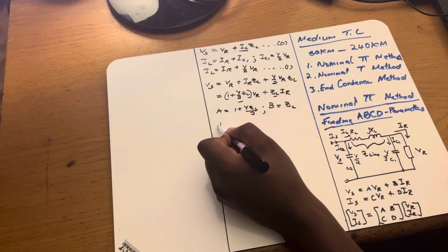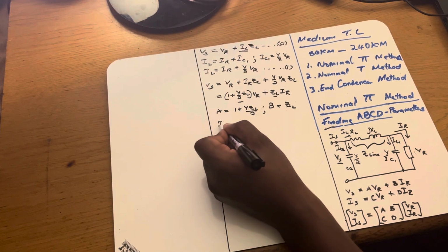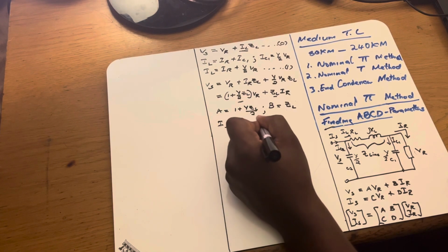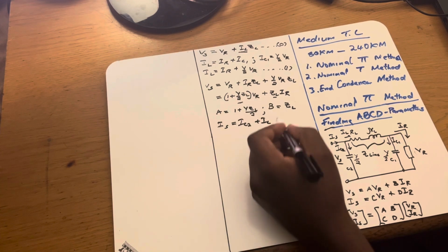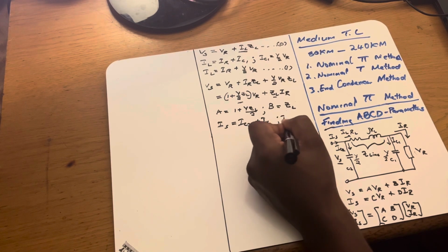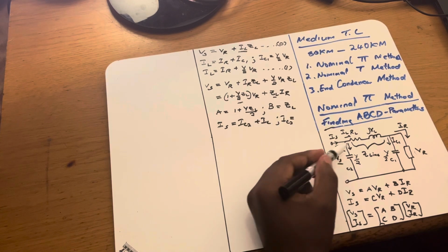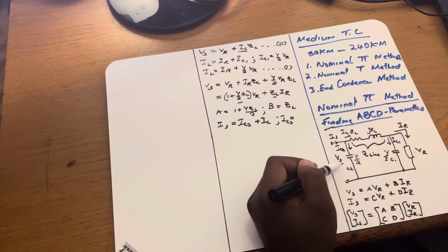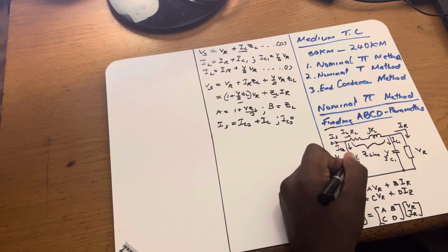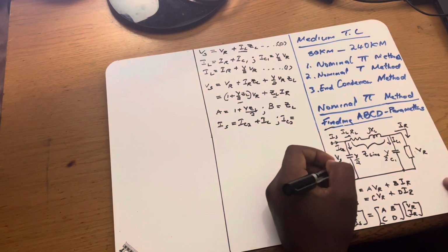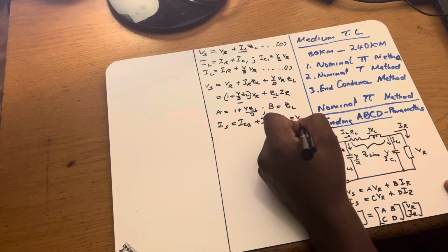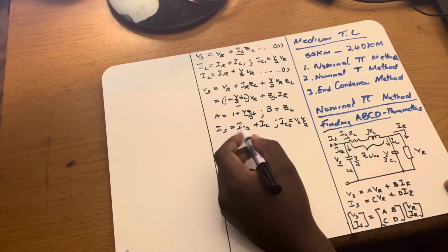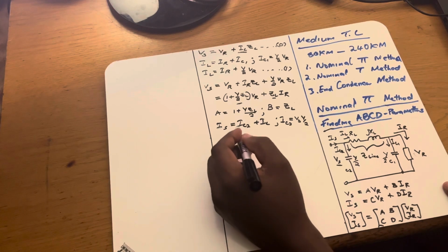So that means IS is equal to IC2 plus IL. Okay, do you know what IC2 is? The voltage sitting across this capacitor is VS. So we multiply this admittance with the VS and we get IC2. So it's going to be VS times Y over 2. We get this current, so substitute this current here in the place of IC2.